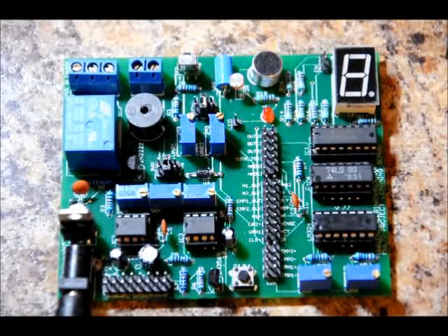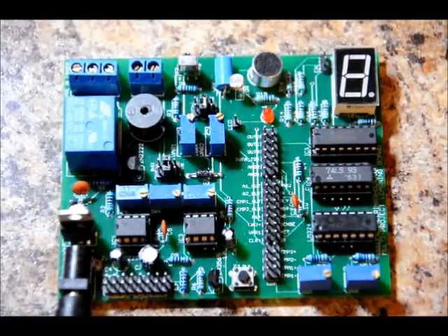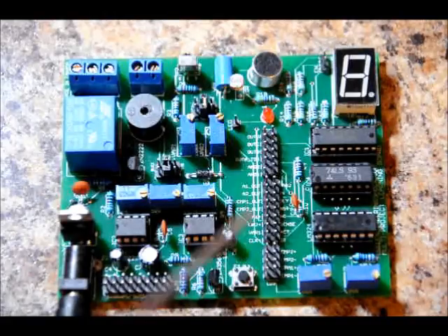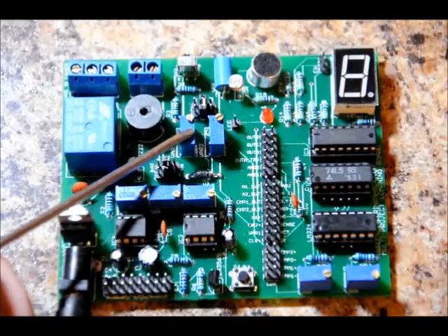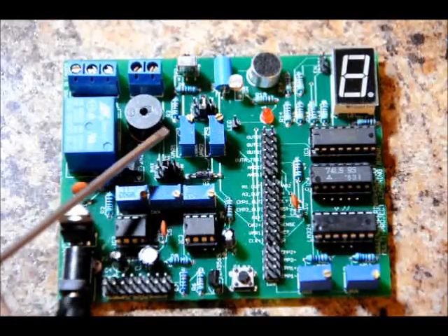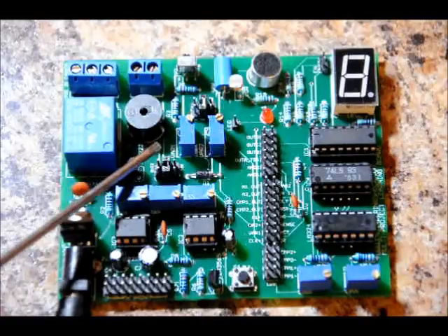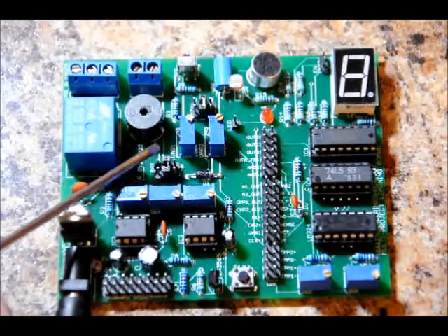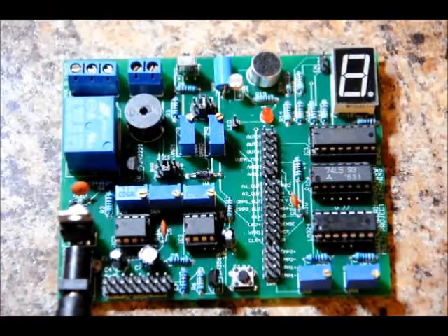First things first, our variable resistor output, our voltage divider, which we're going to set to 2.5 volts, is right here, labeled VAR1. This pin needs to be set to 2.5 volts. This is the tunable 10-turn potentiometer. It's a 100K potentiometer, and the output can be tuned to anywhere between 5 volts and 0 volts, and it's labeled on the board VAR1.